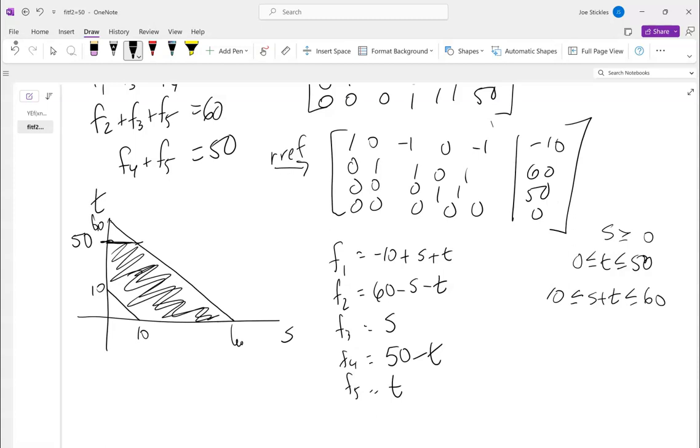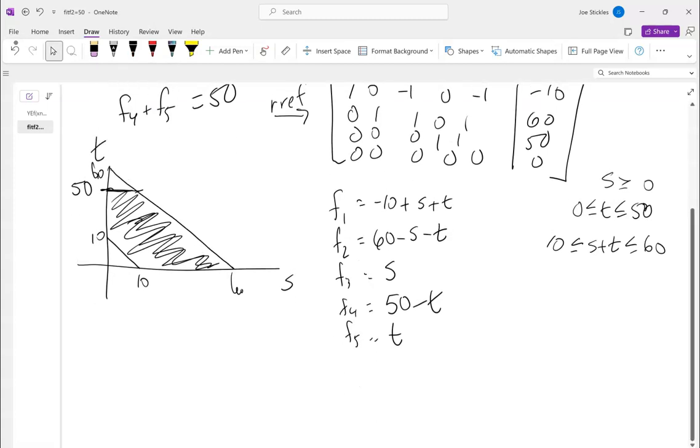So if I look, they've got the currents mapped on here for you. The I1 is the one that's going from this node to this node. These aren't nodes here, it's just going around this way, even though it's squared off, it's a round wire, if you will. So I1 goes from this node around this way to this one. I2 goes just across that one. And then I3 goes that way at the bottom. That makes sense? Okay. So if we were going to make just equations at the nodes, what would the equations be that we get out of that?